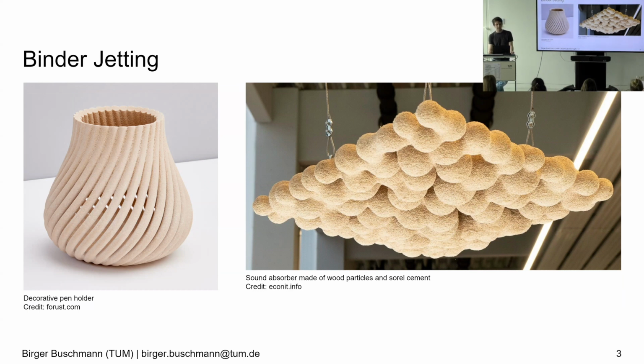It is possible to create very delicate and geometrically complex parts with this process, but there is a drawback. The particle layer only has a density of around 50 to 60% of that of a single particle. This means that there are a lot of cavities in the material, and these cavities have to be filled by the relatively expensive binder. In addition to that, the mechanical properties of the parts produced with binder jetting are relatively low. So usually there is a very cost and time-intensive post-processing necessary to actually use those parts.